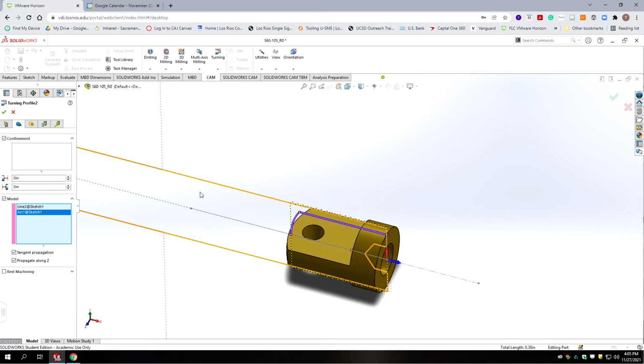we want to shoot past the part enough that our parting tool can come off and start at the model diameter. Okay, so we're going to leave 0 in the front facing and back facing. We're going to go 0.2. Okay, we typically have been going 180 thousandths. We're going 200 because we're going to leave about 20 thousandths of stock on the back face.